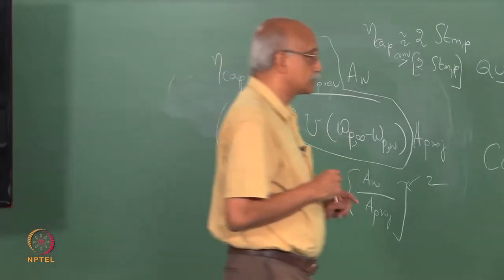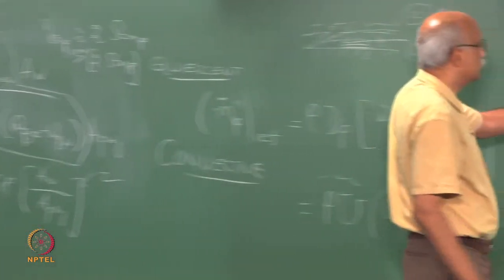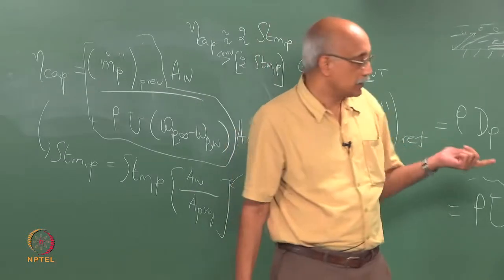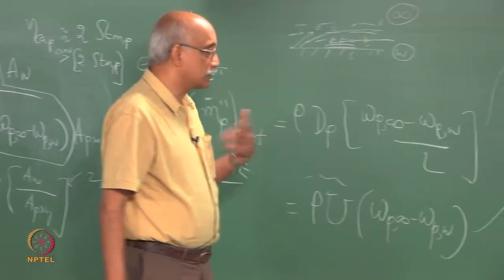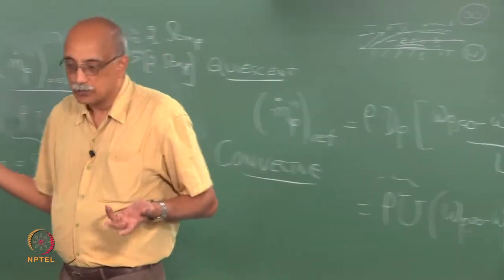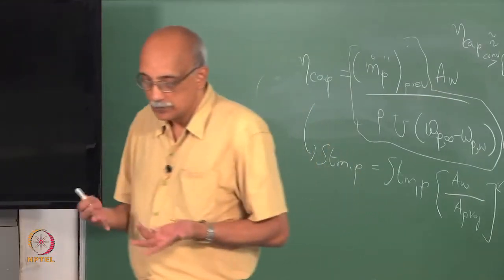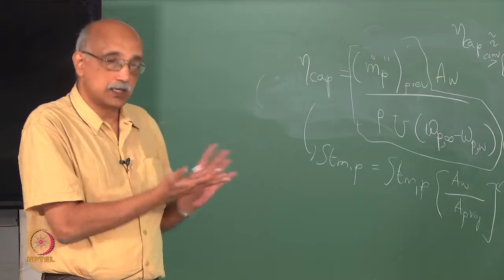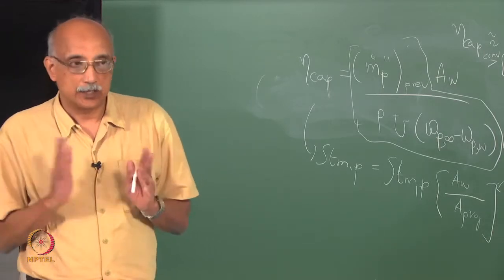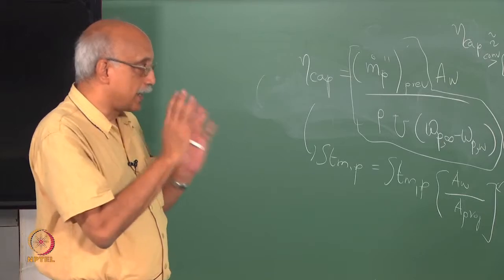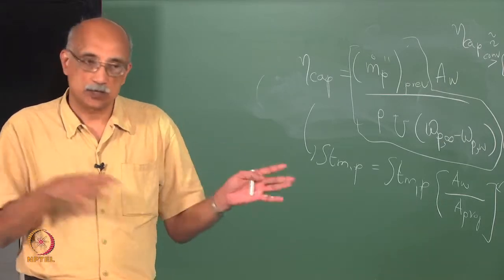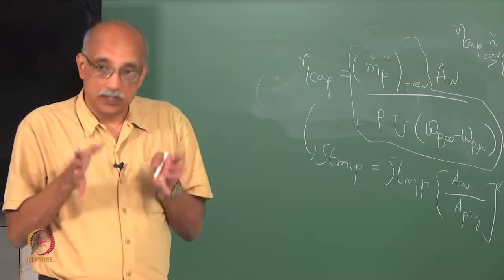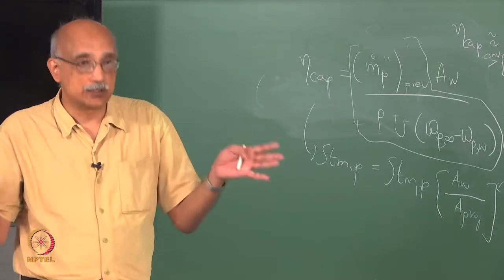Once you know those two parameters for your system, you can do experiments to relate the Nusselt number to the Schmidt number and Reynolds number, and similarly you can relate the Stanton number to Reynolds number and Schmidt number, establish correlations between the two, and because you have used non-dimensional parameters, you can apply your results to virtually any flow situation. Your Reynolds number and Schmidt number do not have to be in the range where you have done your experimentation. They can be outside the range as well.